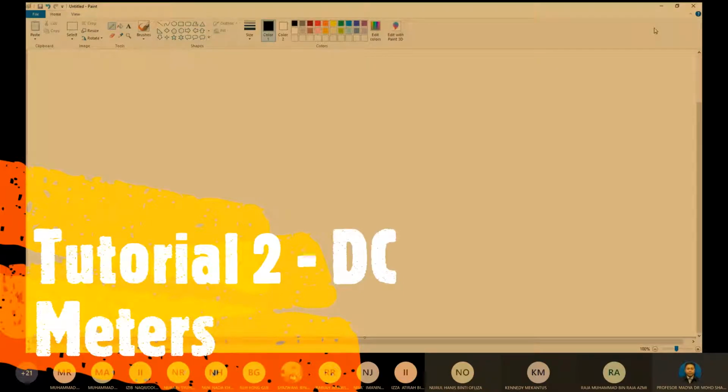figure 1 has the PMMC. PMMC is the permanent magnet moving coil instrument with a coil resistance of RM 99 ohms and full scale deflection current of 0.1 milliampere. The shunt resistor RS equals 1 ohm. Determine the total current passing through the meter at full scale deflection, for A, and then B is 0.5, and C is 0.25 full scale deflection.